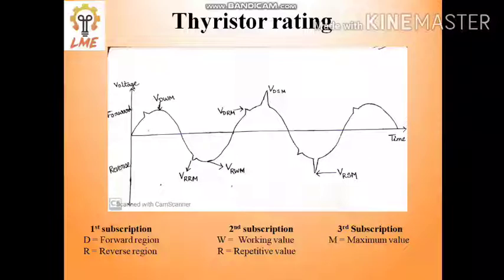Okay, in the second part, what is RWM? R for reverse, W for working, M for maximum. So that is known as maximum reverse working voltage. In the same way, VRSM. VRSM means what? R means reverse, S means surge, which I forgot to write over here, M is the maximum value. So VRSM is known as maximum surge reverse working voltage.